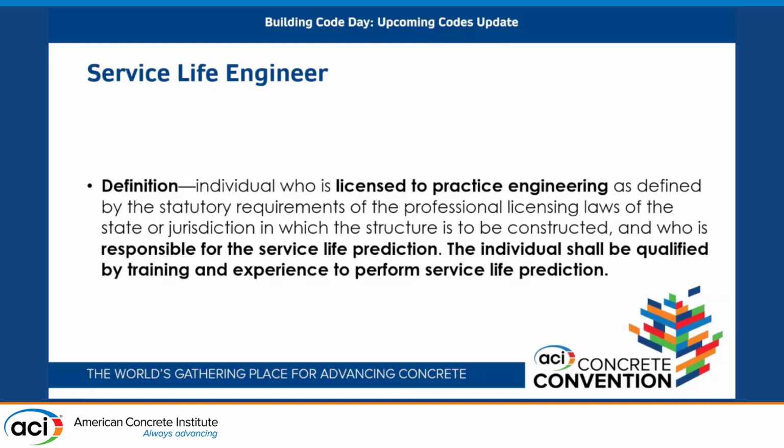So service life engineer, this is perhaps the most important and often discussed part of the design specification. Who is that person or that individual? Anyone who is a licensed engineer in the jurisdiction where the project is being executed. That's a very important part, because it comes back to responsibility. And that individual has to have the competency to be able to discern what are the critical exposure conditions that can reduce the service life of the structure, and has to be cognizant of what are the means and methods that can be used to resist that degradation and extend the service life of the structure overall.